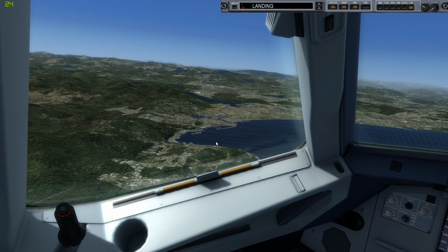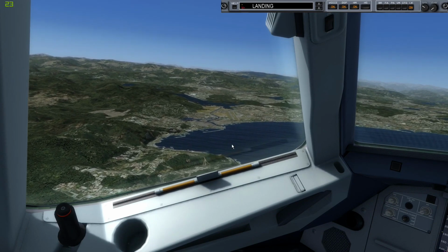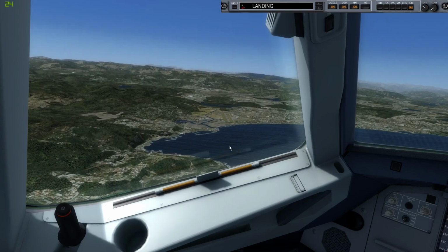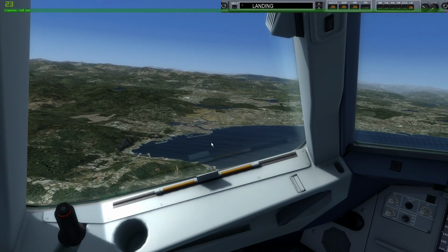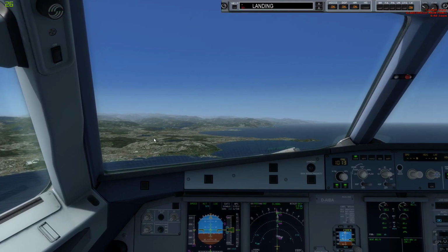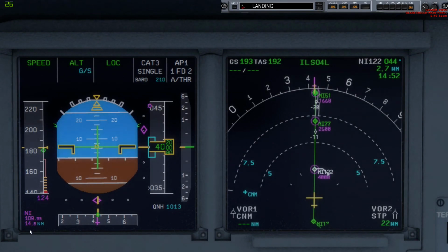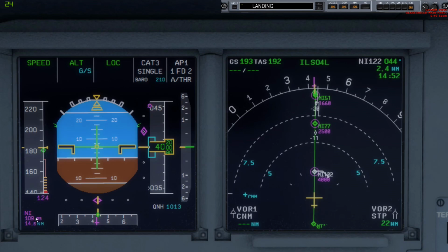Another airport down here, if I may be permitted to use a Yoderism. This is not the airport you're looking for. There's the one we want directly ahead. I'm going to hold off for a while before flaps. If we take a closer look at the PFD, you'll see why. We've still got 15 miles to run before touchdown, so there's no massive rush to throw out the flaps and the gear.